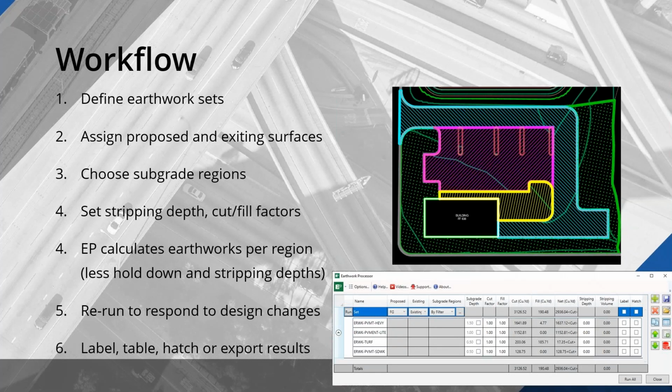So the purpose of this presentation, or this webcast, is to roll up our sleeves and look at how Earthwork Processor functions and how I get it to really work the way I need it to. This step 4, we got 2 step 4s in fact. This step 4, the second one, does a ton of stuff in the background, and the primary focus of this presentation is how is it calculating earthworks for me? That's an important piece of this because we need to be able to trust the tool and what it's doing, because that's a huge portion of the cost of our projects.